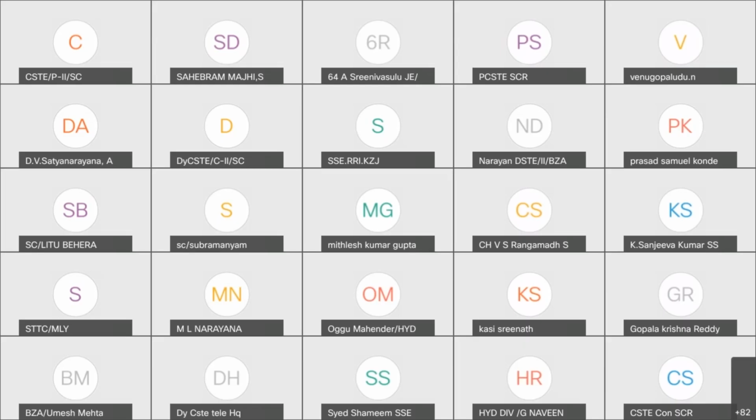Are you getting this problem in almost all TWS machines, or is it an isolated incident? During discussion with my colleagues, I think 5 to 6 point machines have been noticed, sir. And one more thing, the lifting problem is also coming in the 143 mm stroke point, sir. In that also we replaced 2 points, in Chintakani 18B point machine and 12B. After reporting to OEM, they simply replaced the washers in the mechanical fuse, sir.